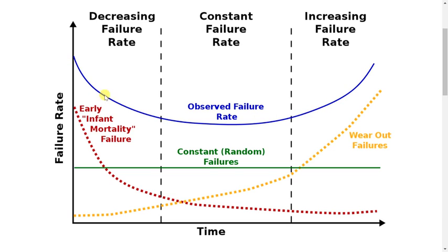And this is our bathtub failure curve, or our bathtub curve. If you ever look at reliability studies, failure modes or failure mode analysis, and FMECAs or FMCAs, failure mode cause and effects, then you're going to see a lot of curves like this, or perhaps sometimes like this, not so much nowadays, and not so much like this either, unless you're operating with a run to destruction maintenance program.